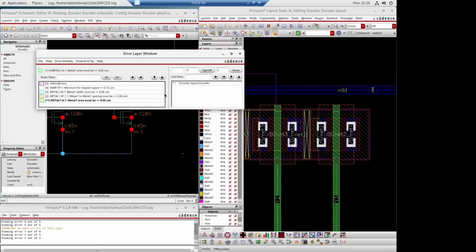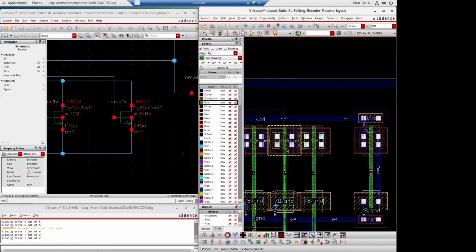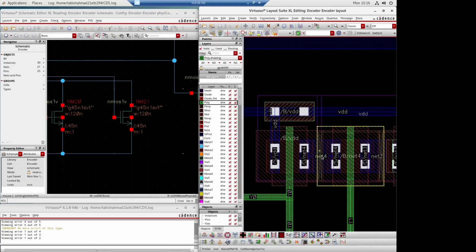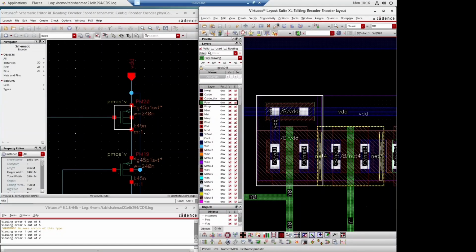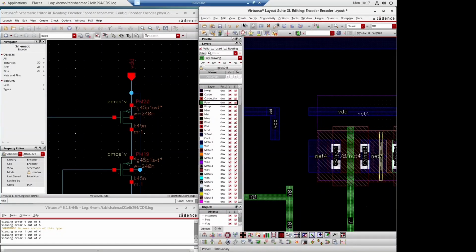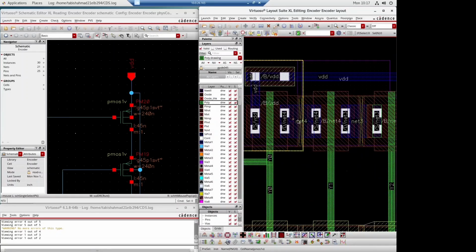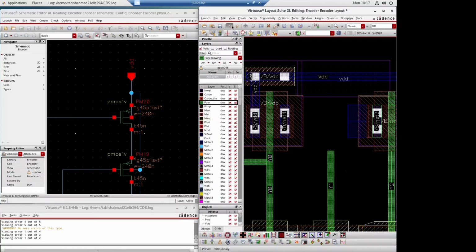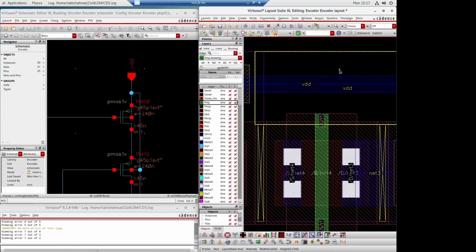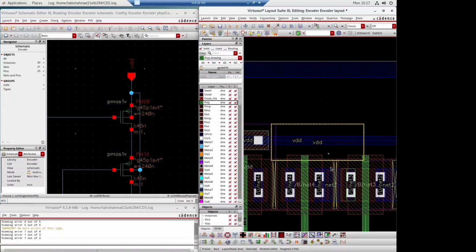First are the off-grid errors, which are very basic, meaning the via placement is not correct, and secondly here you can see the connecting metal lines. This metal line we will delete and connect a new one, as we have moved it a little bit, so these connections are broken. So we will do this again. Make sure to connect every time when you move a PMOS or NMOS.